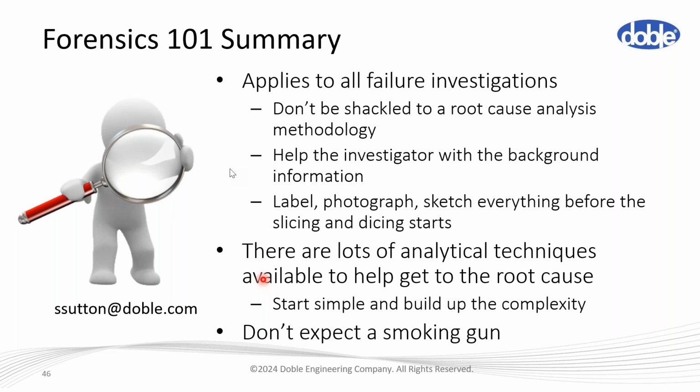However, there are instances in things like oil-filled sealing ends where if there's a leak, either out of the sealing end or on occasions under the sheath of the cable, and the oil level in the termination drops, then you'll pick up PD inside the termination because the oil isn't there anymore.